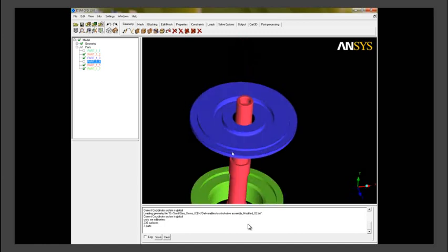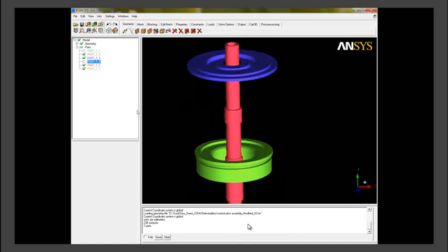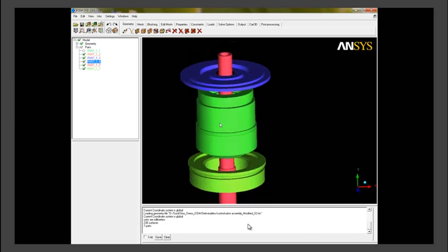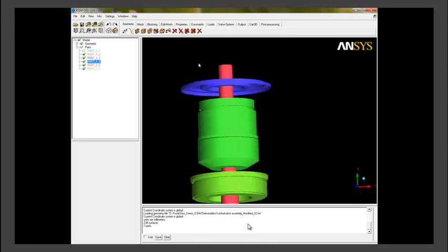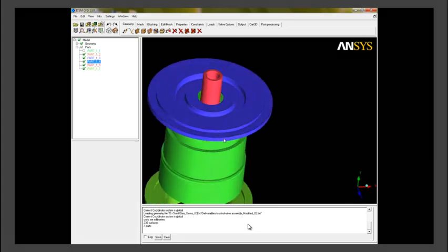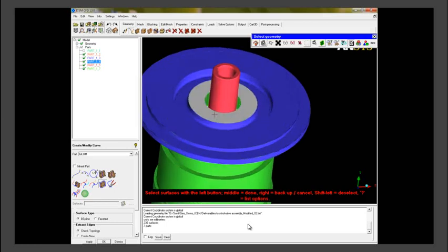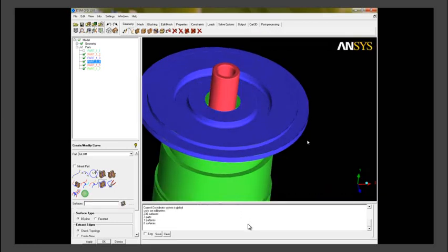We have to deal with one part at a time. Depending upon which volume we want to retain, we modify various parts and surfaces associated with them. We will also need to create additional curves in order to modify or create additional surfaces. So the first step is, using the existing surfaces, we create additional curves by using the create modify curve option.